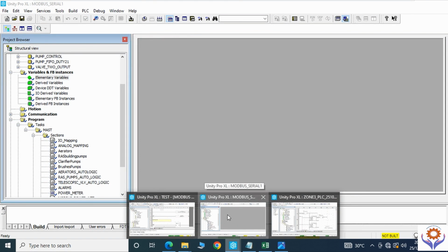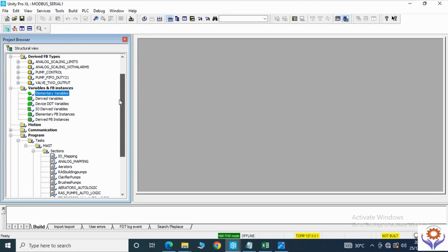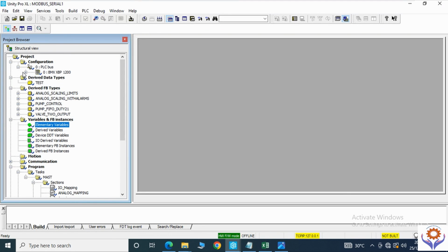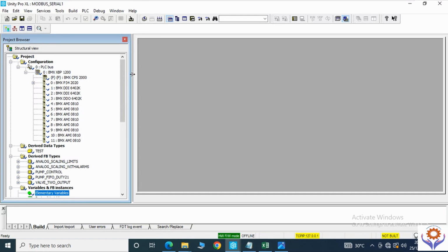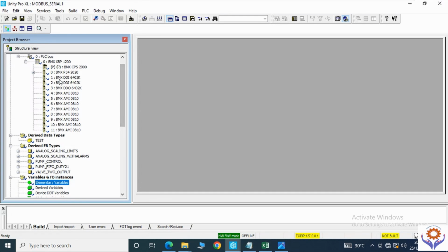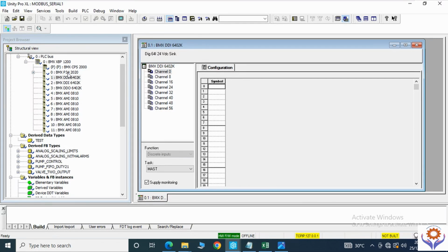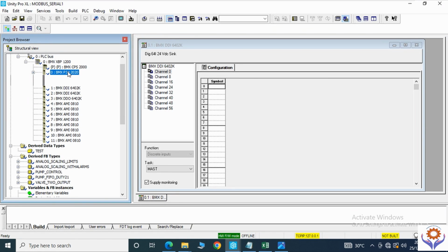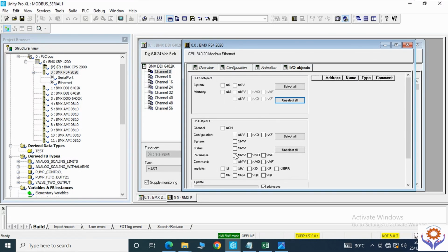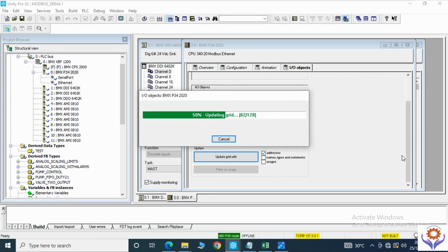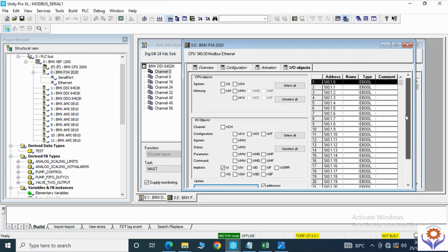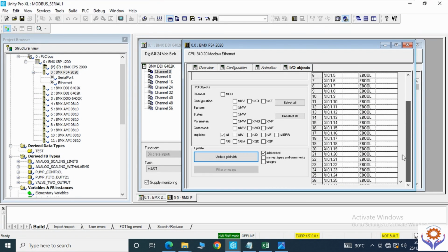See here, for example, you already created one application. Just for example, you created one application. If you watch my video from part 1, all the parts, you can understand that I already made some registrations. See here, just click open and you can find all the IOs here which we used. All these, like percentage I 0.1.0, all the registers we already mapped before.